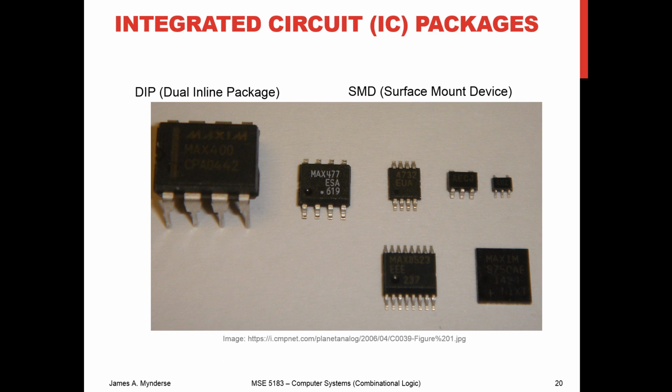So when we put all this stuff together, we get these integrated circuit packages. The dual inline package is what we're using in class. It's got pins on one side, it's got pins on the other side, and they have a gap between them, and the gap between them means you can put them into a breadboard nicely.